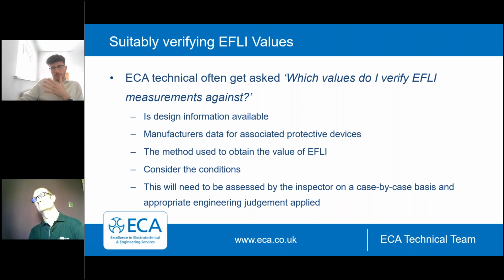Ambient temperature, if we're measuring that, is generally going to be on-site guidance note 3. But circuit loading, as we've seen, is a massive factor here. It's going to cause heat. So for example, if you're carrying out an EICR, and let's say you've arranged to temporarily shut down a piece of equipment to conduct an earth fault loop impedance test to confirm ADS. Now that equipment may be a piece of machinery that's been running for several hours. Based on that, the conductors could be at operating temperature if they're near to their current carrying capacity.